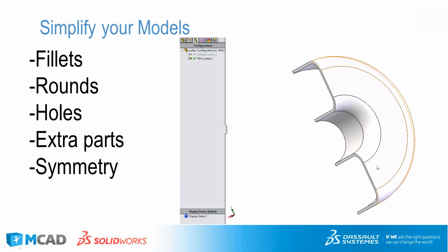It's got laser etching on the outside of the face. It's got all the manufacturer info. It's got really, really fine minor notching right there. All these tiny, crazy little features that you would have a nightmare trying to mesh, but don't actually contribute to the structural integrity of the part. For example, especially the laser etching or very slightly inset embossed text. If you tried to mesh that, it would have a nightmare of a time trying to squeeze elements into the thinness of a laser etched word.